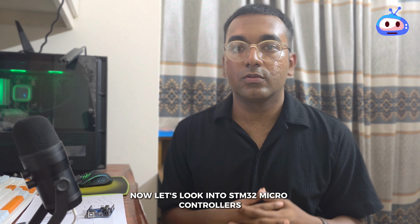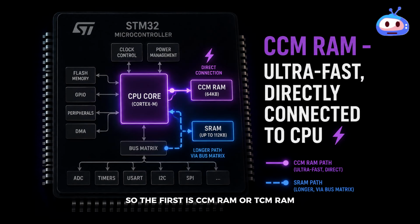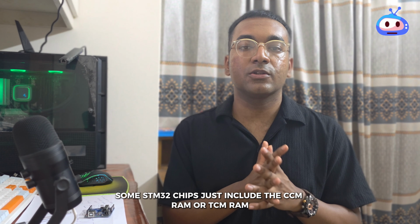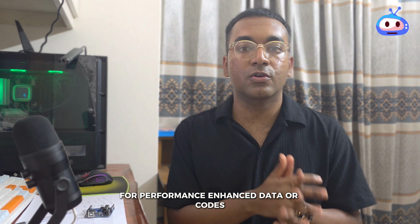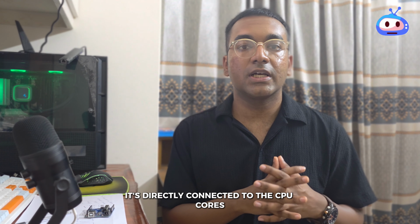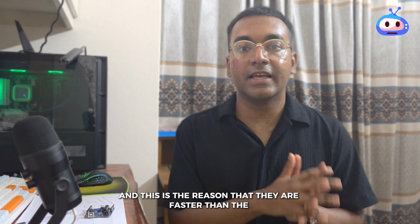Now let's look into STM32 microcontrollers. They have their own set of specialized memory for speed and persistence. The first is CCM RAM or TCM RAM. They're the fastest ones. Some STM32 chips include CCM RAM or TCM RAM for performance enhanced data or code. Think of it like a VIP route for the most important data. It's directly connected to the CPU cores, and this is the reason they're faster than the SRAMs itself.